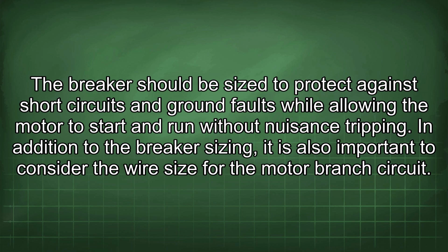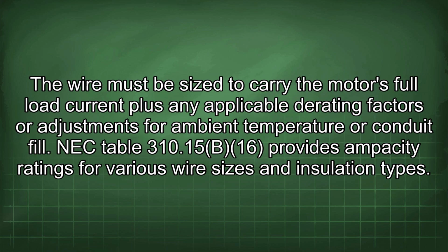In addition to the breaker sizing, it is also important to consider the wire size for the motor branch circuit. The wire must be sized to carry the motor's full load current plus any applicable derating factors or adjustments for ambient temperature or conduit fill. NEC Table 310.15(B)(16) provides ampacity ratings for various wire sizes and insulation types.